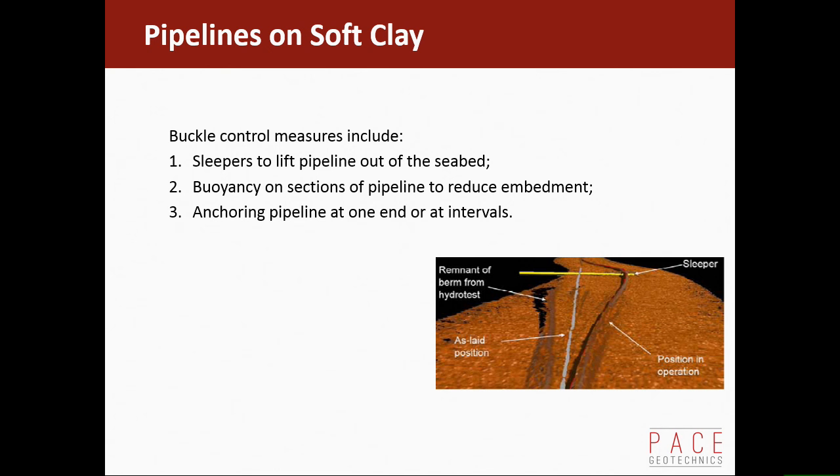There are some issues to be aware of with that, and this happened to BP on one of their jobs. Because it's going up and then down, you're promoting slugging of the contents of the pipeline if it's multi-phase. So the oil tends to collect just before the sleeper, and then the pressure builds up, and then all of a sudden that slug of oil goes through and gas follows it, which is changing the weight of the pipeline, and that cyclic change of weight stresses the pipeline potentially, and it actually starts to trench itself into the seabed.